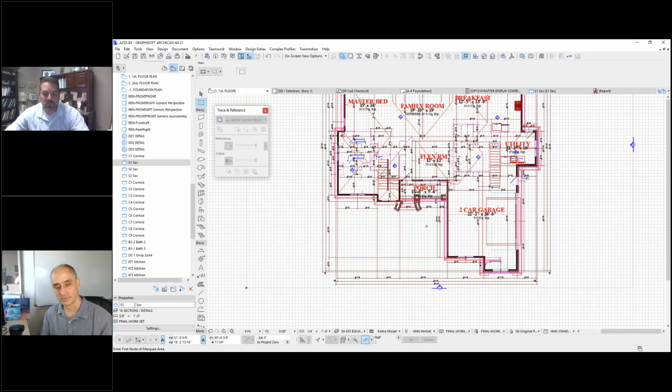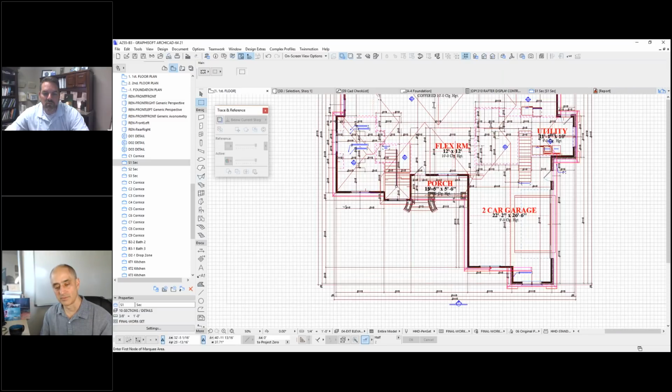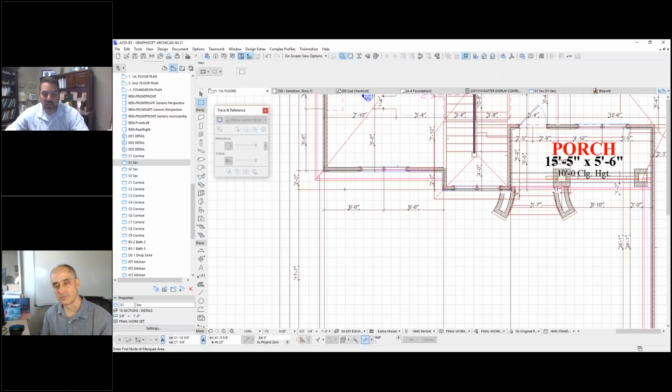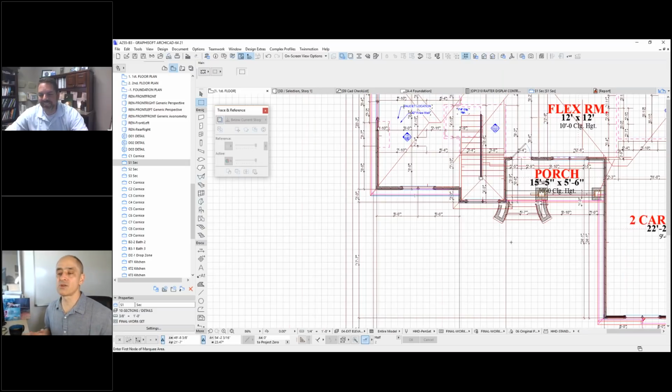It's an object, but if you wanted to carve back the rake, you can cut the rake back. Some of what you had there seemed to be sticking into the roof, and you would just make this the operator and make the roof the target and just subtract. Oh yeah, I'm sorry. Yes. So that's very straightforward.